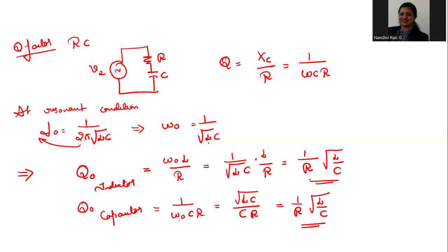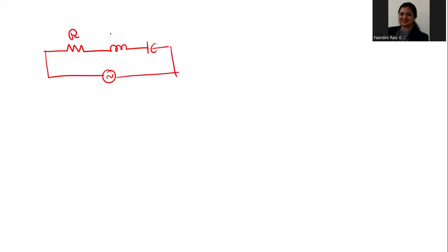Next, we have to write the equations in terms of voltage and current for the series circuit. So previously I mentioned inductor and capacitor as L and C. Now let me write them as jXL. What should I write here? Minus jXC. No confusion, right? About minus. Okay. R has VR. Voltage across XL is VL. Across the capacitor, VC. The overall applied voltage is V.